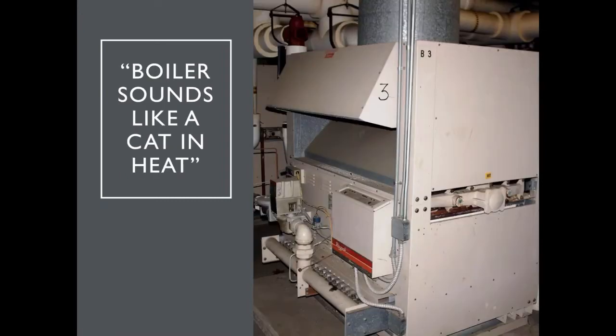So how about this for a service call? The guy called me and said, Ray, sounds like we have a hot and heat when our boiler's firing. I'm like, what? So I go out there, and here they had jumpered out. There's a copper fin boiler. He had jumpered out the flow control on here. And sure enough, I thought it sounded like an orca whale, you know, and I felt like Jacques Cousteau. And so we had to clean the whole heat exchanger out. It was all scaled up.